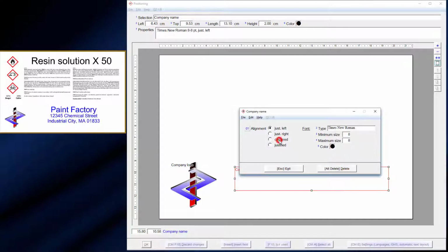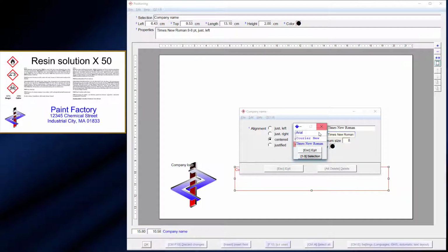First we choose the option, Centered, for the alignment. The selected font is Arial. You will notice that only the standard font types have been provided. The reason for this is that the label fields are automatically filled by the program and therefore every character that is theoretically possible in all languages has to be displayable. Many of our customers are not aware of it, but almost all available fonts have a reduced character set and would output non-displayable characters as squares, which should be avoided by using only these fonts. You can install additional fonts, but at your own risk.